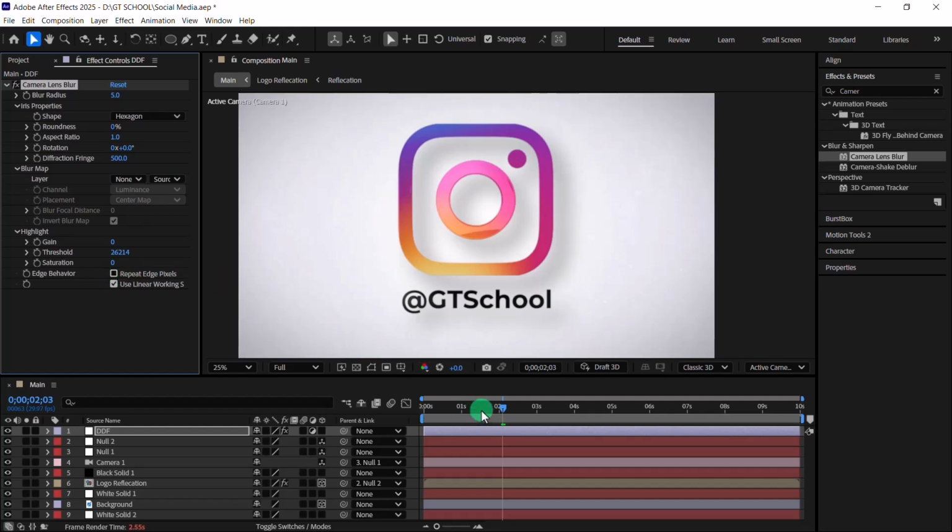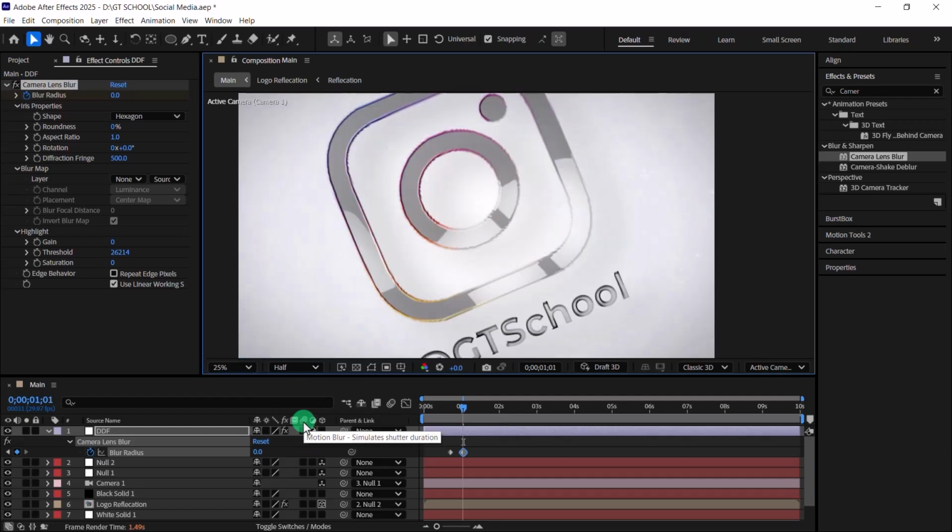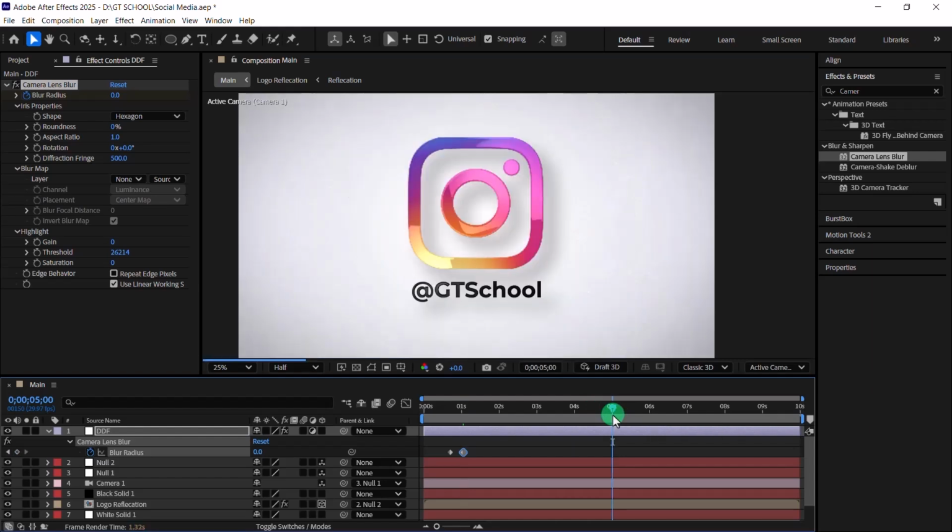Go to 20 seconds and something like 21 seconds, and create a keyframe on blur radius, and let's change this to something like 30. Press U on the keyboard to preview the keyframes. Go to frame 1 and 1 and change this to something like 0. Go to something like 5 seconds and also click here a 0, something like this.